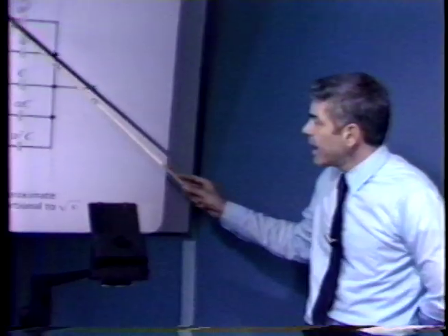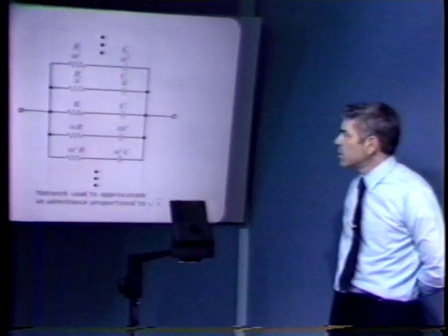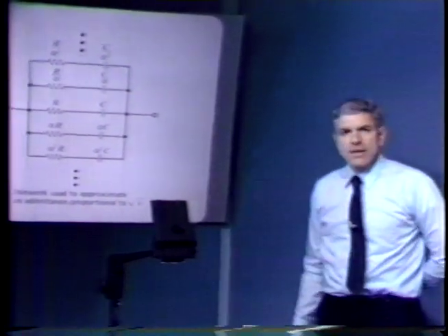And you can control the amount of ripple really by the closeness of spacing of pole and zero pairs, or equivalently by the choice of the quantity alpha in this network. Well, it turns out that if you use only 1 pole and 1 zero per decade, you get a very, very good approximation to 45 degrees of phase shift associated with the transfer admittance.